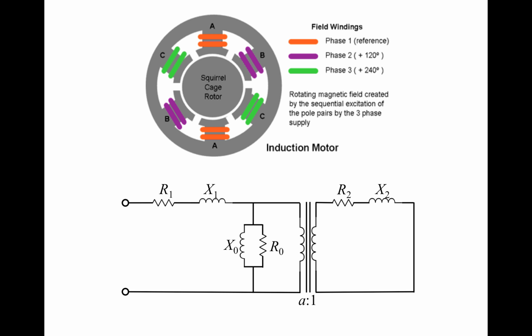So when we try to actually compute the mechanical power and the torque later on, we need to remember that this kind of diagram is per phase, right? And we need to multiply by a constant factor of 3 to account for the fact that we have 3 phases, right? All the results derived by looking at just this diagram give us the result for just one phase. So we need to multiply by 3 to account for 3 phases.